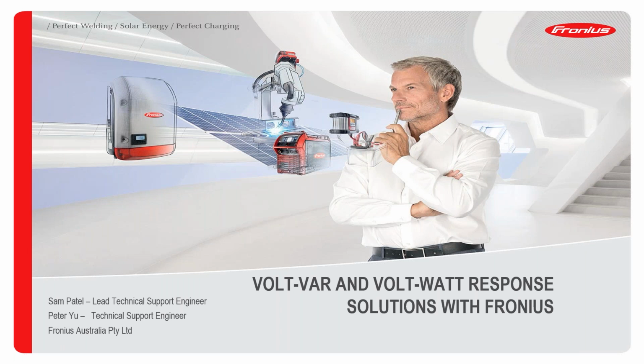Sitting alongside me is Peter. He will be covering a few slides on how to enter the Volt-VAR settings on a Fronius inverter. He will show you how to calculate the Volt-VAR values using the Fronius Excel tool, and how to enter those values on the screen of a Fronius inverter. Hello everyone, this is Peter here from Fronius Tech Support.